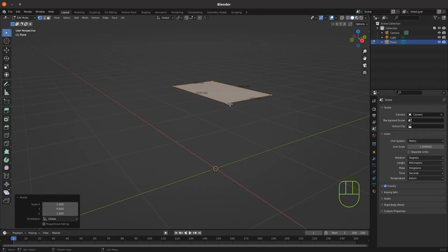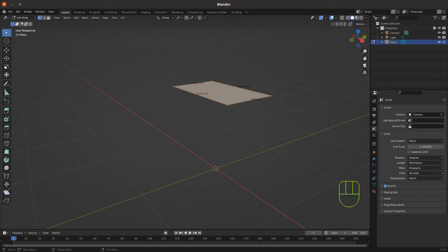Now the bottom of the framework, I'm going to add some casters to mine so it won't sit directly on the floor. You have to compensate for the height of the casters. I've got some 100mm diameter casters which are good for rolling over fairly rough workshop floors, and they sit 130mm high off the floor. So we need to extrude this plane now on the z-axis minus 870, which will leave you the gap